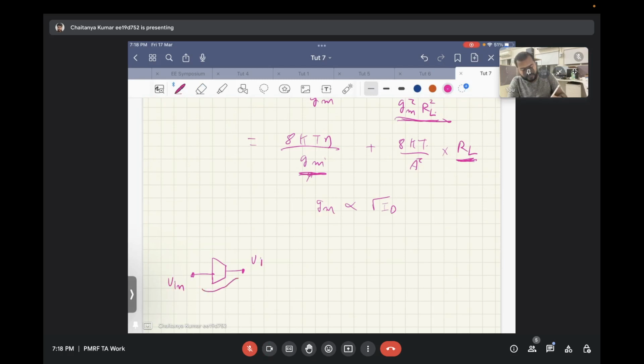So you have achieved maximum gain that is achievable to not saturate this voltage. That is what dynamic range scaling is, right? Yes, sir. Before saturation. Yes, exactly. So there is some gain from the input to this internal node, let's say A.